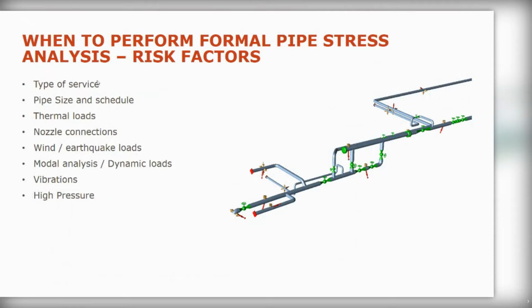Pipe size and schedule. So size maybe is less important, but the thing with bigger pipes is that they exert more force on nozzles and connected support structures. So for larger pipes, you want to make sure you make those checks, maybe not for the sake of the pipe failing, but for things that are connected to the pipe failing, because a large pipe expanding or moving or catching a lot of wind could break structures and tanks and things around it. Schedule is the same. If you have a thicker schedule, it's a bigger rod that's pushing on everything, so it has more strength in it.